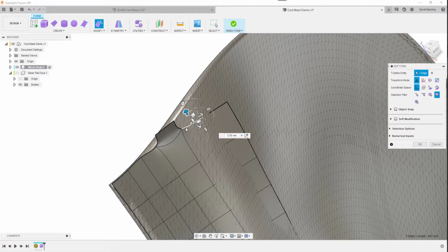And I can do the same thing over here, Alt, and it will add that in, and I can do it there as well, or alternately I can Control Z, undo that, select that and that, holding Alt, and it'll add in another surface. Now obviously that may not be the best thing.